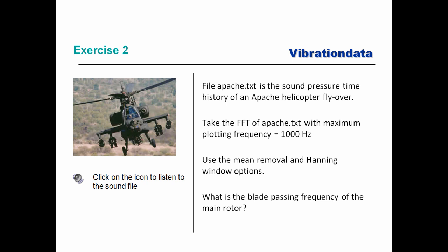What is physically going on to cause those frequencies to occur? And that energy can be forcing frequencies, or it can be natural frequencies excited into a resonance or whatever. But we have to be data detectives, and we have to go out and sometimes gather further information, like looking at that mill standard as we did, to try and determine and identify what is going on with our data.